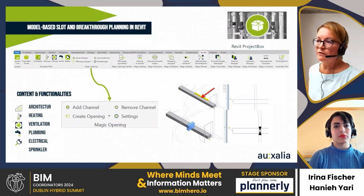The workflow we're introducing starts with the MEP team. They use tools like Magic Opening and Magic Opening Transfer within the Revit project box to create and manage openings. These tools are really powerful because they allow the openings to be associative, meaning they'll automatically update if the MEP model changes.